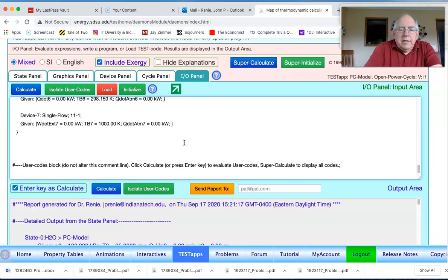And so the eta, let's call it the eta of the process heater, is going to be, in the numerator, what comes out, which is m dot 7 times the psi value at state 7. Okay, so that's the flowing exergy coming out of that process heater.